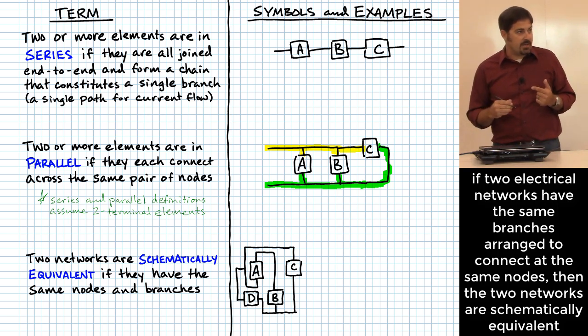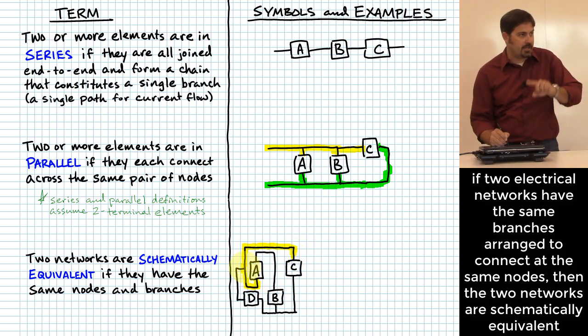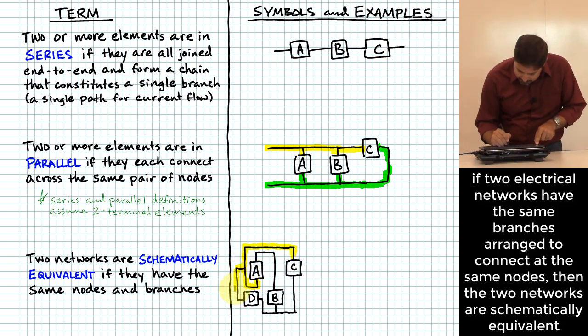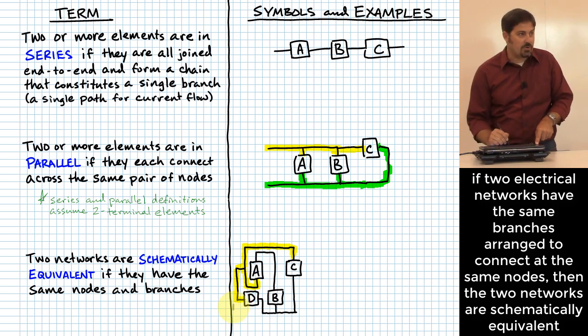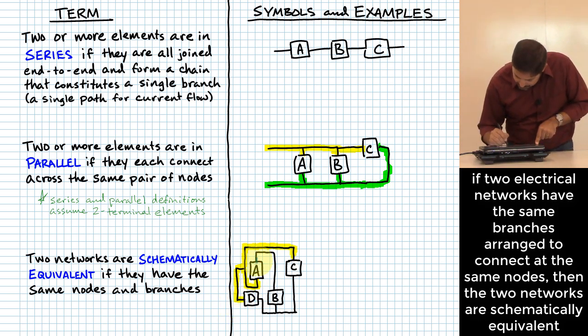As you do this, in my opinion, the easiest way to do it is to drop some kind of a highlighter on one of the wires and color in every direction until you hit an element, right? So I colored all the way I could go in that direction, but did I have any other places where it peeled off? Yeah, I had one over here, and that goes all the way there. Have I colored everything for that node now? Okay, I have. Now, let me go and color another one.